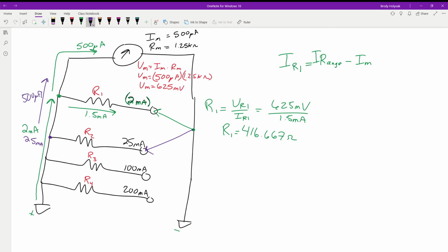Is it connected in our circuit? If we physically move this switch, yep, when we move the switch, we are no longer connected to this. This is a what? An open. What's this? An open. What's this one? A closed circuit. We have a complete current path. Okay? So yes, we have 500 microamps going up this direction. How much current do we have coming through here? 24.5 milliamps. Because we have a complete loop.